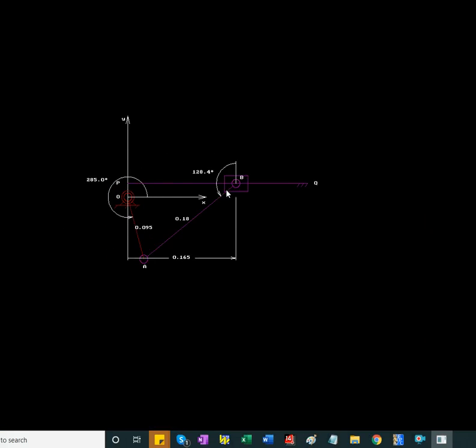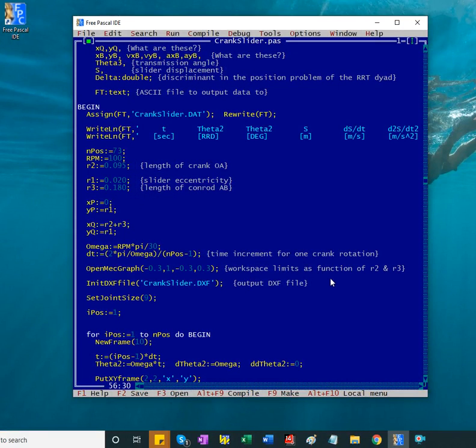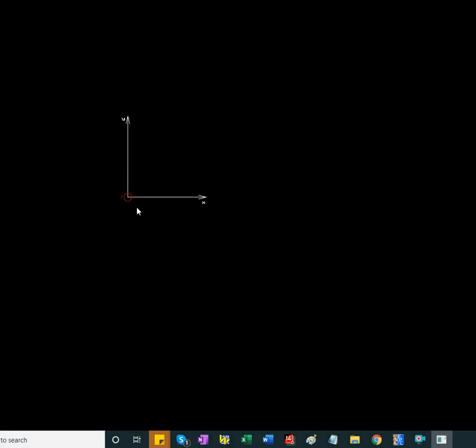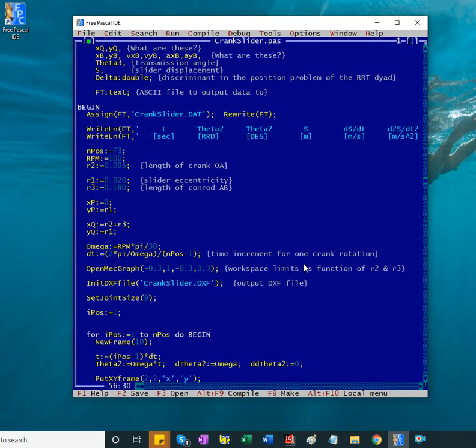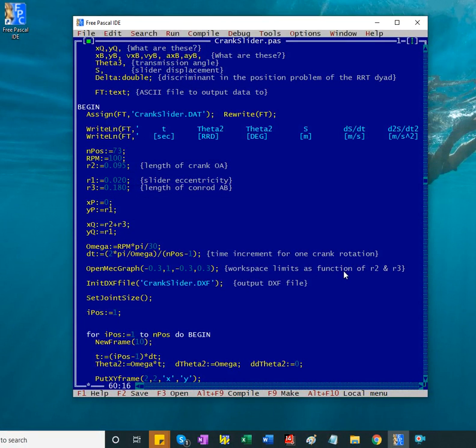So it looks a little bit better, but smaller than before. The proportions or the size of the motor symbol, the joint, and the slider and the joint again, as well as the ground, three hatches showing the ground connection, are governed by the set joint size. So if I change this to 3, it will look much smaller. Okay, as you can see here. Text font size stays the same. So let's make it, whatever it was, 9, 7.